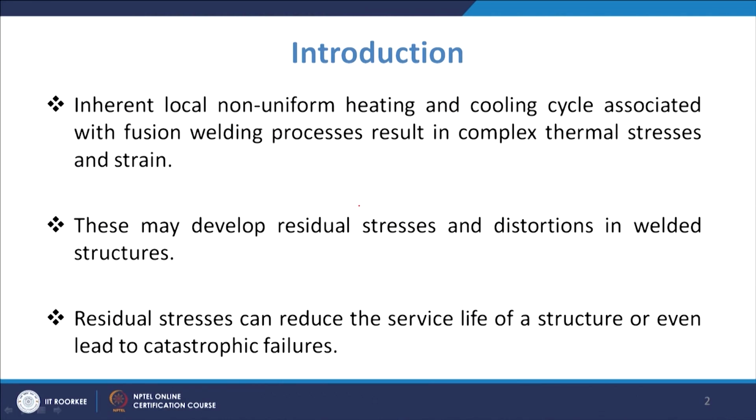As we might have studied, some stresses are good for the body and some stresses are not good for the component. So, we will have some discussion about the definition and concept of residual stress development, and also we will talk about the types of stresses which are there inside the body. Let us first see the inherent local non-uniform heating and cooling cycle which is there in the case of fusion welding.